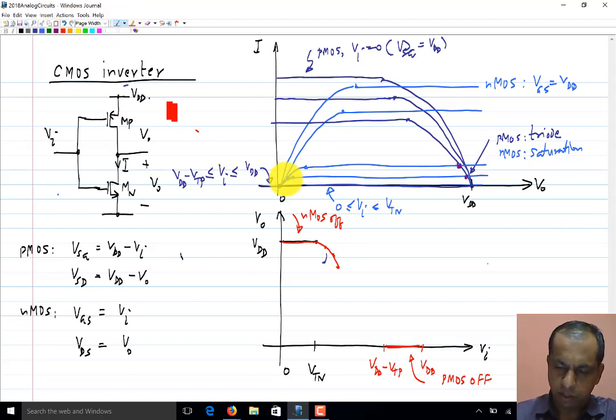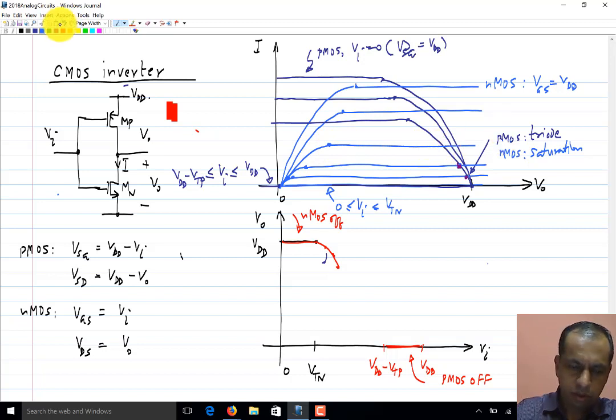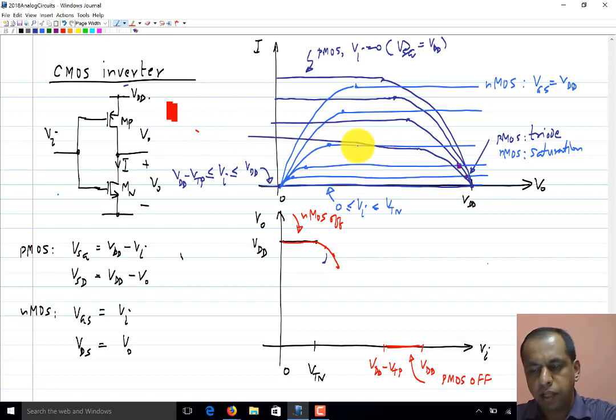Finally we reach a point where both transistors are in saturation region, and as with the previous cases, when this happens the gain is very large. Small signal wise, this means that in saturation region gds values are very small for both the NMOS and PMOS transistors.